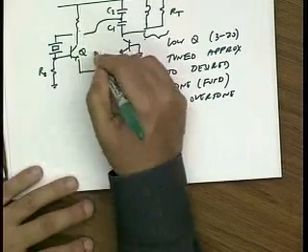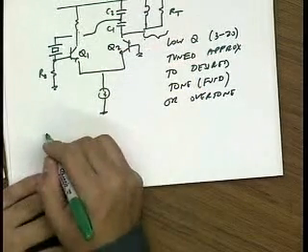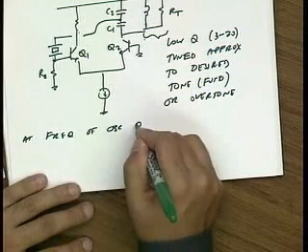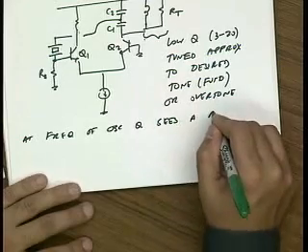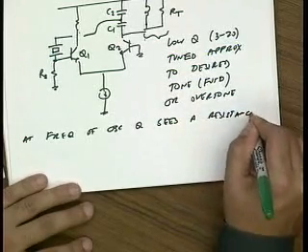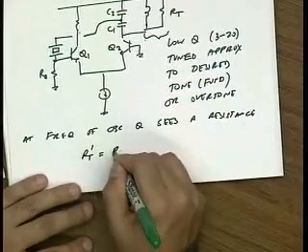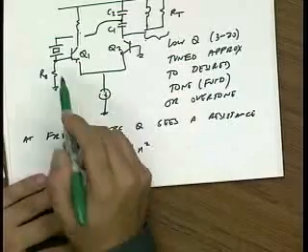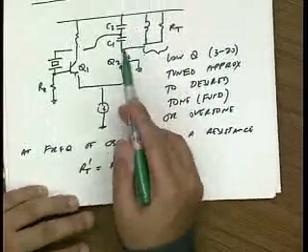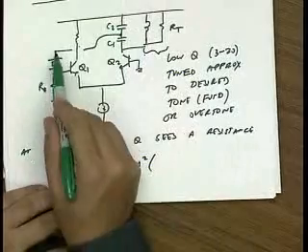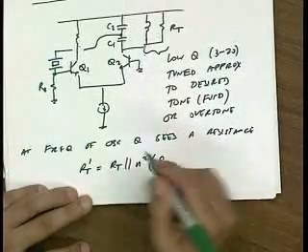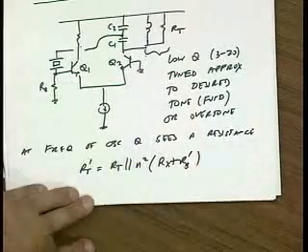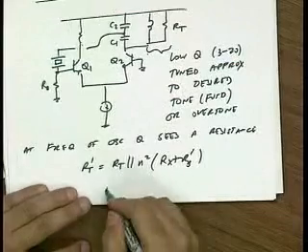So the transistor Q2, at the frequency of oscillation, sees basically a resistance, because it's in resonance, R tank, which is this RT in parallel with N squared through this cap divider, times the resistance of this guy, Rx, in series with RB prime, which is RB in parallel with, let's say, the diff pair input impedance.